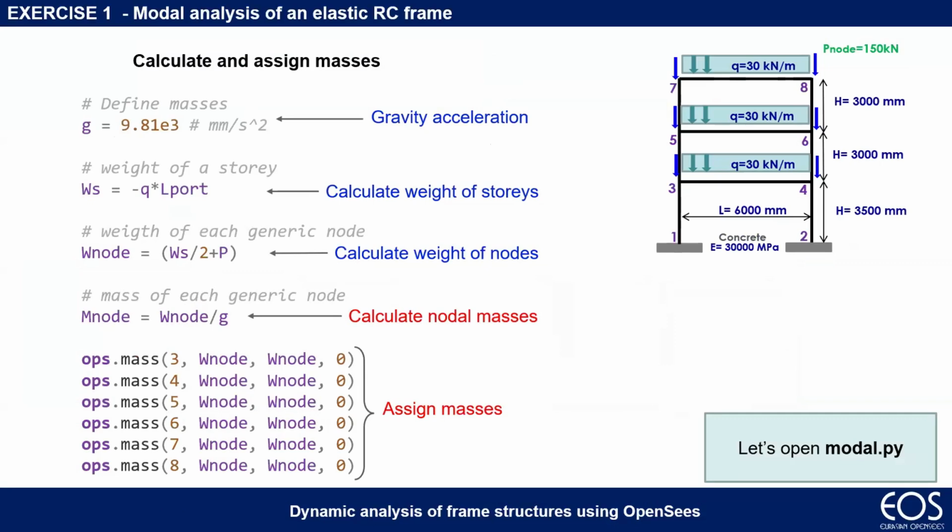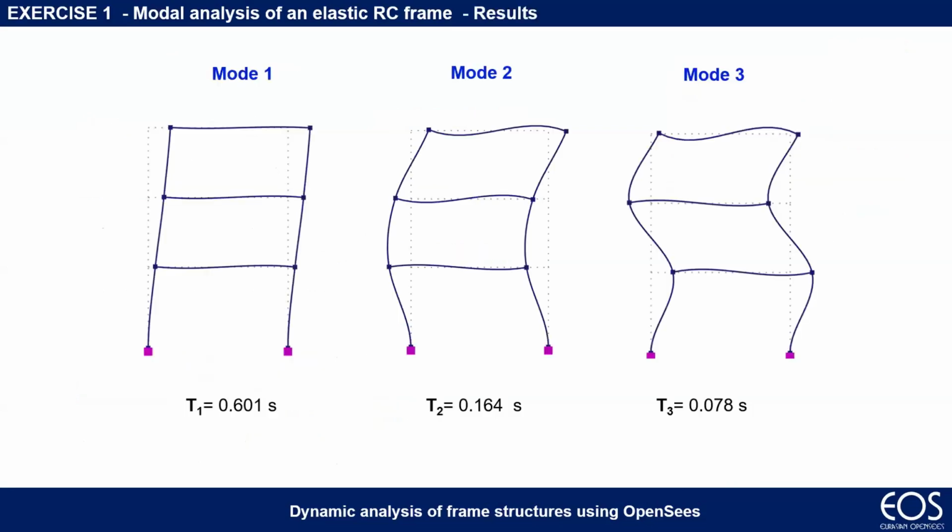You have to pay attention to just one thing: the system is a 2D system with 3 degrees of freedom. So I have to declare 3 masses. If the mass is 0, I have to declare 0. Is it clear? Okay, perfect. I have to declare a number of masses equal to the degrees of freedom of the system. If I don't want a mass on that degree of freedom, I have to declare it as 0.